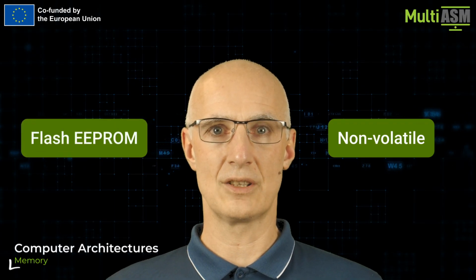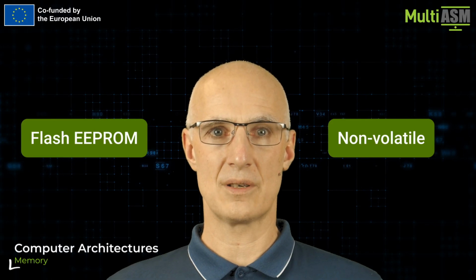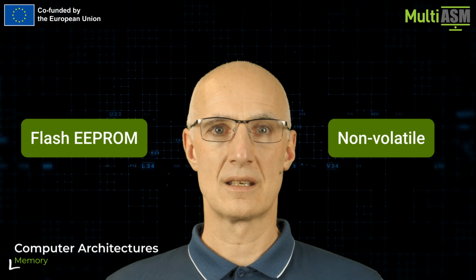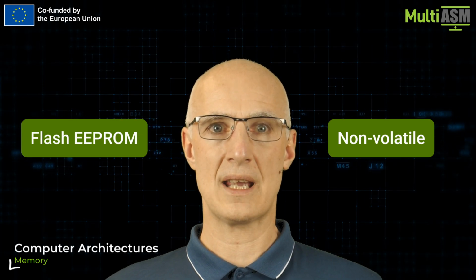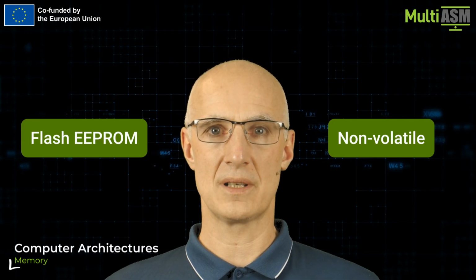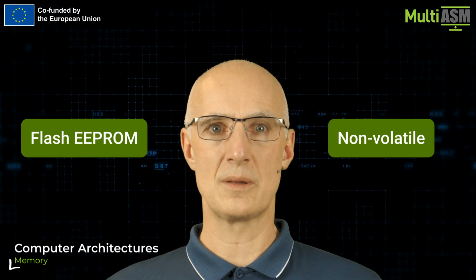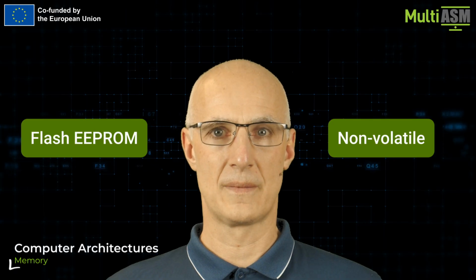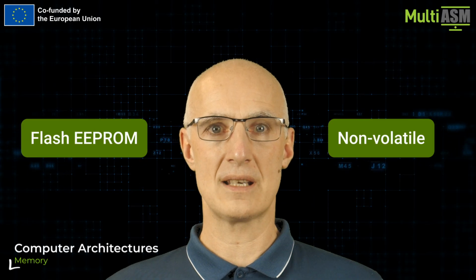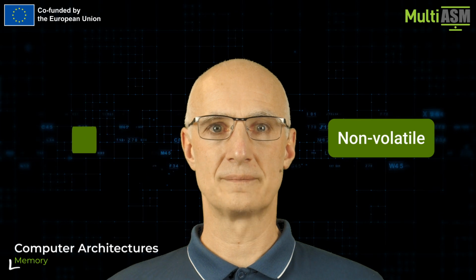Flash EEPROM is a non-volatile memory that is similar to EEPROM. Whilst in EEPROM a single byte can be erased and reprogrammed, in the Flash version, erasing is possible in larger blocks only. This reduces the area occupied by the memory, making it possible to create denser memories with larger capacity. Flash memories can be implemented as elements on a larger chip, making it possible to design microcontrollers with built-in programmable memory for the firmware. It is the most popular non-volatile technology at the time, enabling firmware updates without the need for any additional tools or removing the processor from the device.